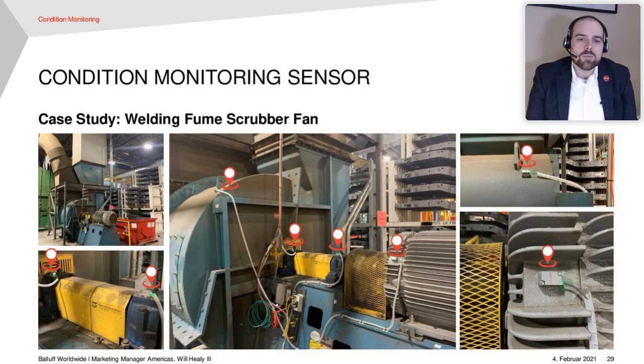So these fans can accumulate buildup on the fan blades. It can be hazardous; it requires hazmat training and confined spaces training to go inside this thing and clean the fan blades off. And especially if something gets damaged or broken, it can be a huge hassle to try to repair this. You have to take the whole thing apart.